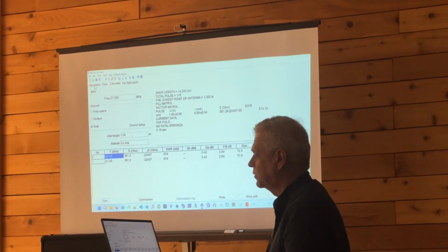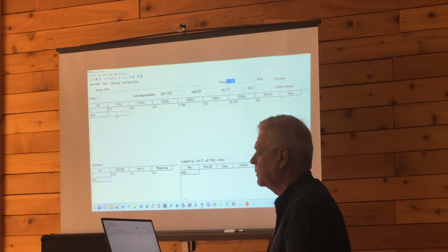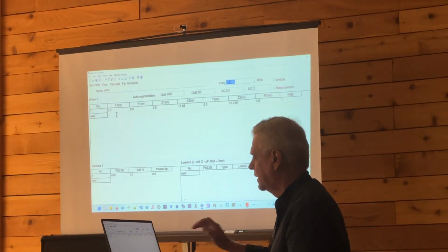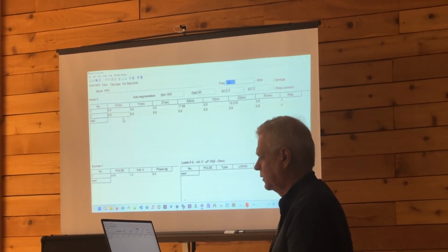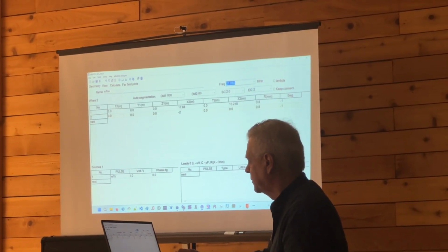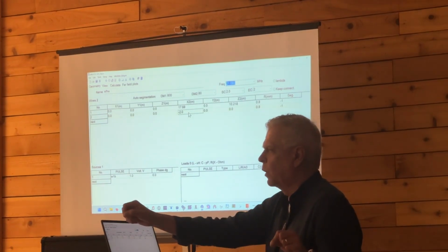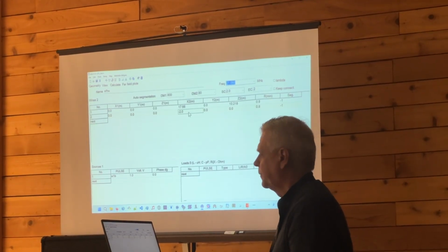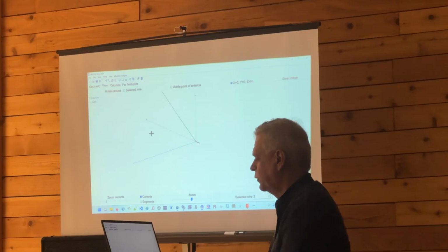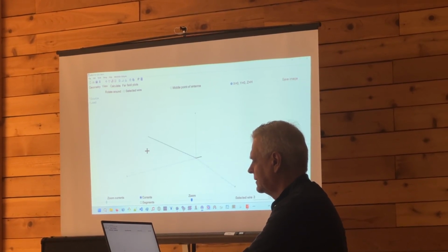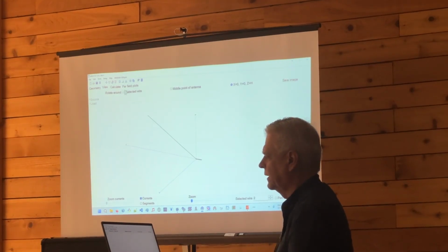So let's go back to geometry. And now, remember we heard about adding the pigtail, or my counterpoise, go ahead and add that. Let's say the origin is going to be the origin, but for x2, I'm going to put it at -2 meters. Why? I don't know, like a 6-foot coax. The sheath of the coax is going to be my pigtail. Now, I go to view, always go to view, it's always good practice, just to make darn sure I haven't done something silly. No, it's collinear, it's on the XZ plane, and there's my little pigtail here, he's fine.